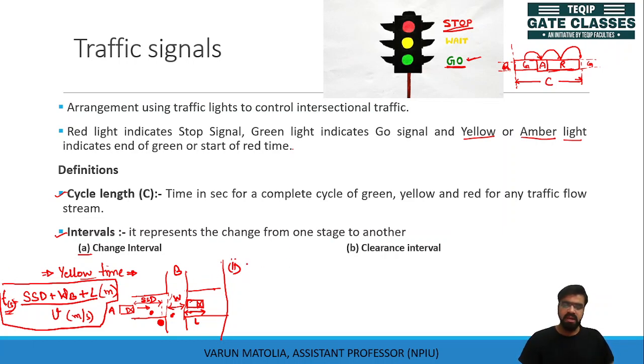So the time provided for the vehicle, in seconds, should be equal to the reaction time and then the stopping distance, the reaction time and the stopping time, braking time. So we can call it the reaction time plus the time which it takes to stop itself before the intersection. The time will be its initial velocity v divided by its deceleration.